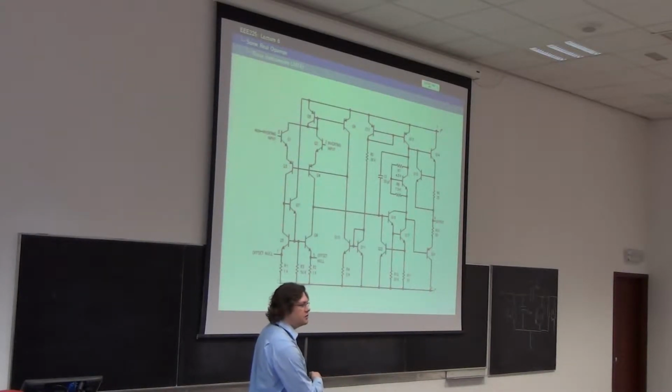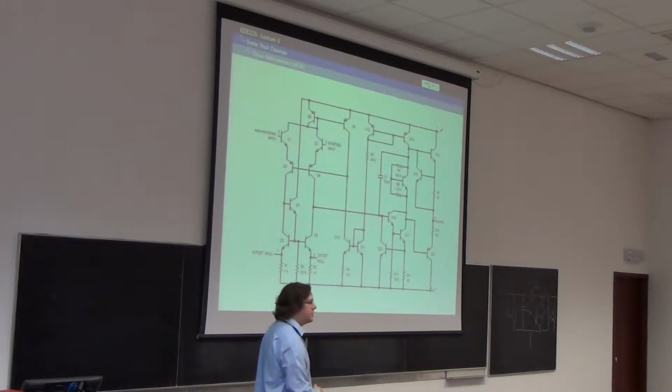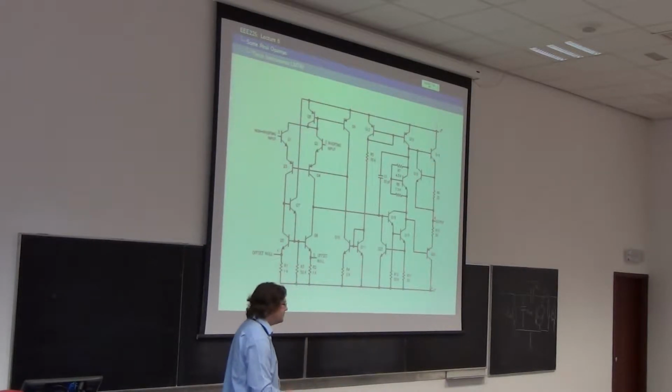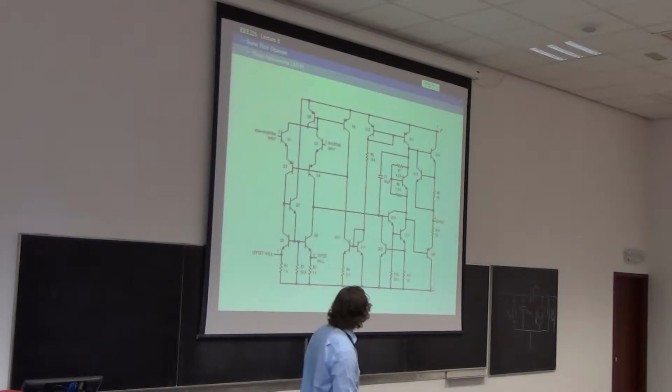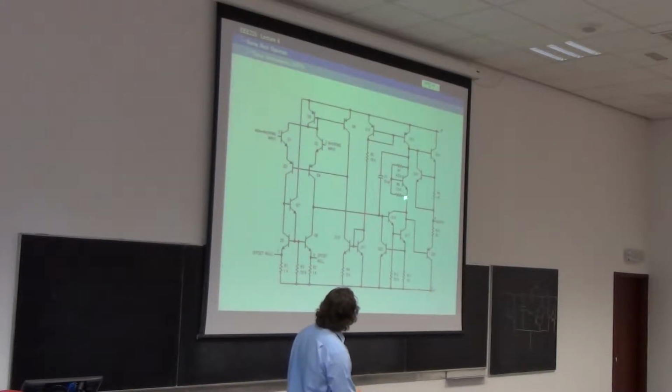All of these styles of circuit originate from a person called H.C. Lin, who published essentially the standard op-amp. He just dreamt it up one day. I don't really know how it worked. There's probably a history of how it happened as well as a paper about it. And since then everybody's used that design because it's got so many benefits and so few drawbacks. So we've got a Darlington, and we've got a VBE spreader or an amplified diode or whatever you like, and we've got an output stage.